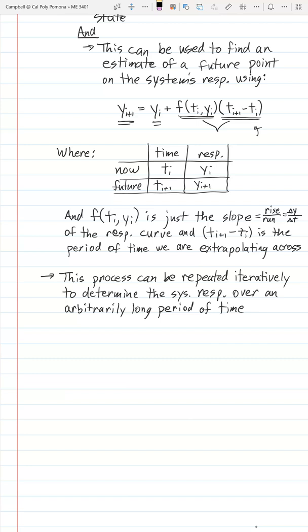In that particular case, we were able to say, okay, we'll check in here, understand what that vehicle is doing, and propagate it, seeing how the errors are creeping in. Then we'll say, okay, now the error might be getting a little too large, so we'll do that orbit determination process. Maybe, I'm going to arbitrarily say 4 days. So we would understand within 4 days that we would start accumulating too much error in our propagated trajectory, and so we would check in on day 3 rather than day 4. And then we would reset everything and start propagating again.